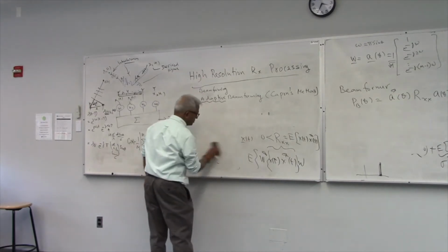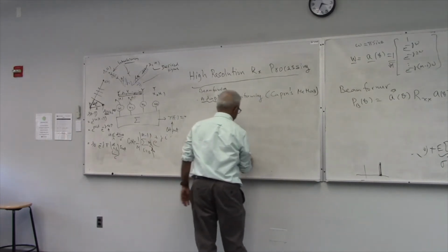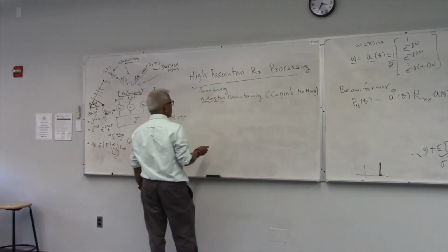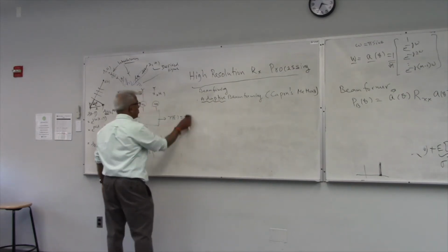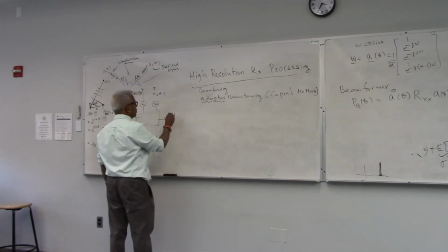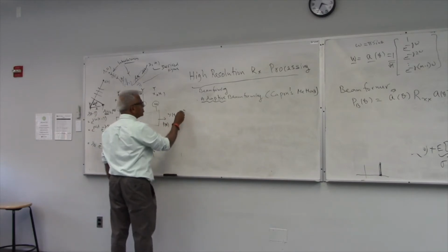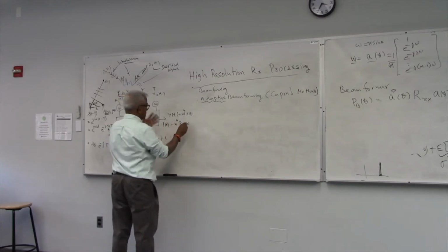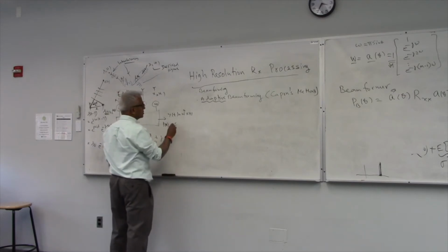So in this one, once again we will keep W of t as the weight vector. The weight vector is unknown. Remember, the output is still y of t, and y of t is W transpose x of t. The output power is W transpose RXX W, in other words the expected value of the square of this, y of t squared. That's W transpose RXX W.